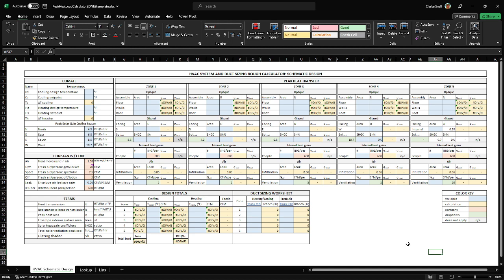What do we have? What's going on over here? If you look at our assignment, there's a definition of cooling design temperature and heating design temperature. It's very simple, but if you look at it in engineering textbooks or spreadsheets, it looks more complicated because there's always a percentage associated with it. You're simply saying, out of all the hours in the year, how many are above this temperature or below this temperature, based on heating or cooling?